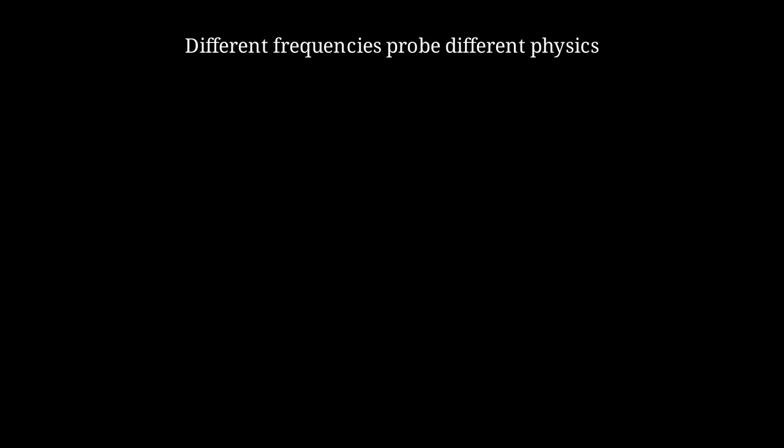Now let's talk about something really powerful, the frequency dependence of dielectrophoresis. The Clausius-Mossotti factor depends on the frequency of the applied electric field. At different frequencies, we're probing different physical processes in the particle. This gives us frequency-selective manipulation.